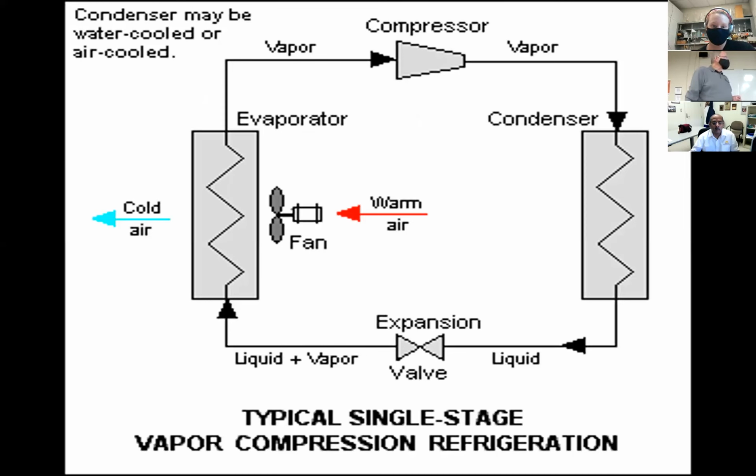And so that's the wonderful world of components. The 5-component system again: the refrigerant that acts as our transfer media, the evaporator where we do the work in the room of cooling the air down, either freezing or refrigeration temperature, taking this vapor that is created of the refrigerant, having this process of converting it back, first compressing it down, from really volume reduction is what we're doing in the compressor,